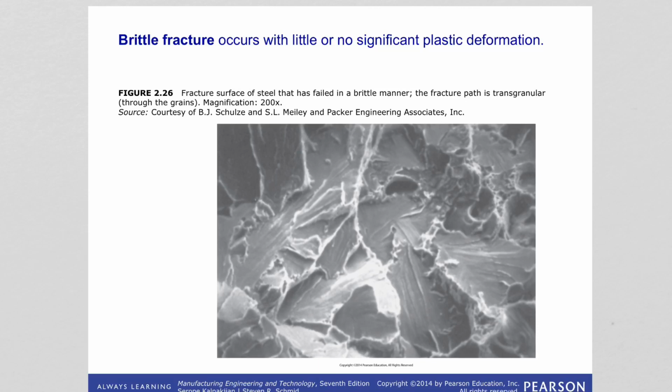So we learned ductile fracture. What about brittle fracture? Of course, brittle fracture doesn't happen with plastic deformation. Either it is very little or not at all. Usually brittle fracture does not happen with FCC metals. This is because of their packing and the number of slip systems. Brittle fracture is more common for BCC and HCP metals.